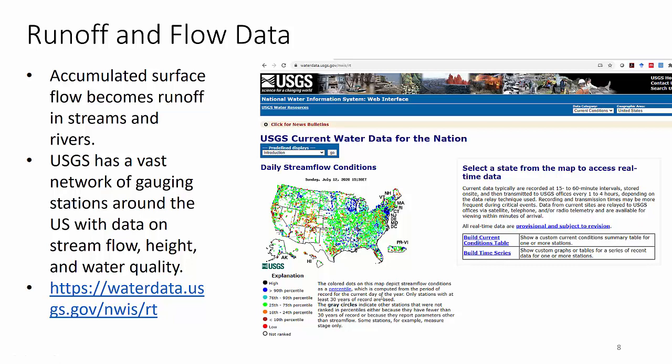So you have to have 30 years of record in order to get these percentiles. The blue dots represent areas where you have greater than 90th percentile flow, and the red dots areas where you have less than 10th percentile flows. And the greens, of course, are in that 25th to 75th percentile, that is average. So think of this as your active flood map: what streams are flooding, which streams are in drought conditions.